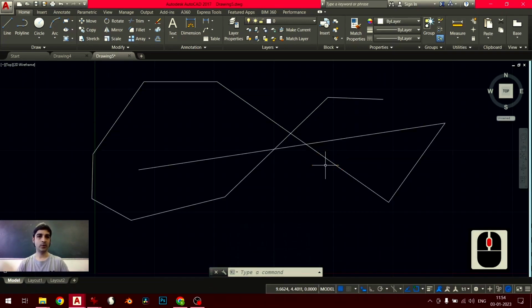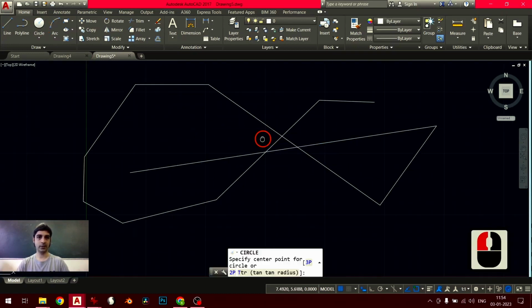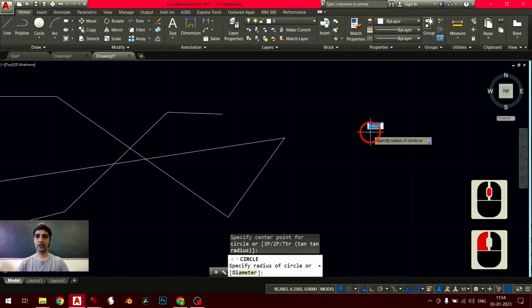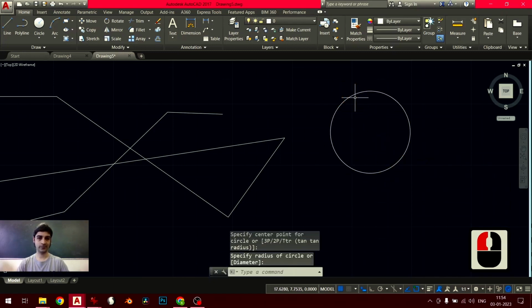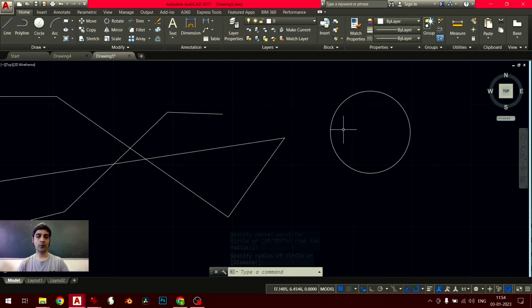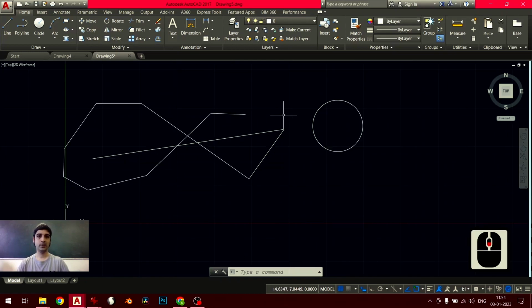So that's the basic way you input any drawing objects. If you want to make a circle, for example, you just click on that tool, click somewhere for the center, and then you can click again and you make a circle, right? But of course, AutoCAD is a precision tool, so there's lots more ways that you can input these objects and get a lot more precision that way. We'll look at that in a few moments as well.